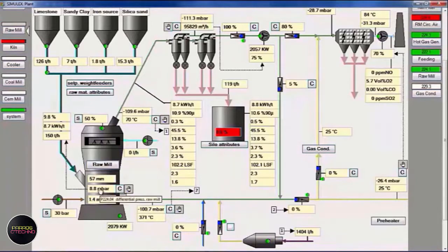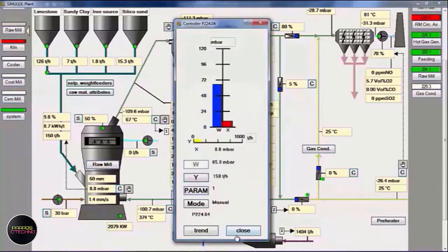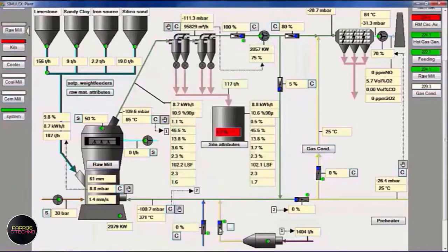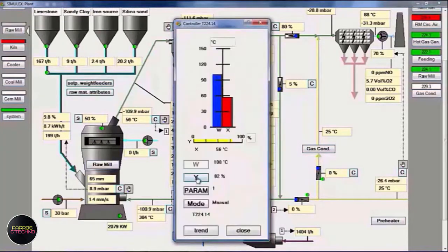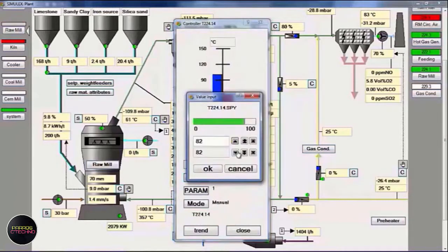The delta pressure is 8, and the bed material is still low. Okay, let's add more feeding. We add 50 tons, to 200 tons per hour. Since the oil use was still lacking, we lowered the return valve another 5%, from 82 to 77%.